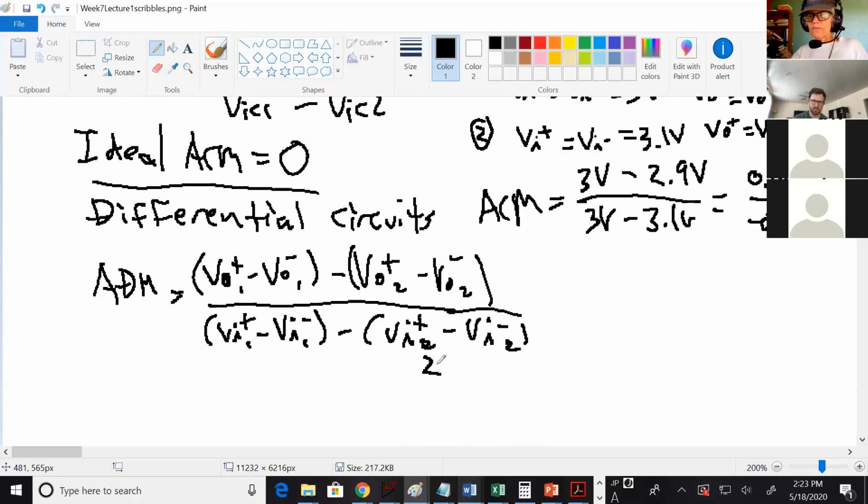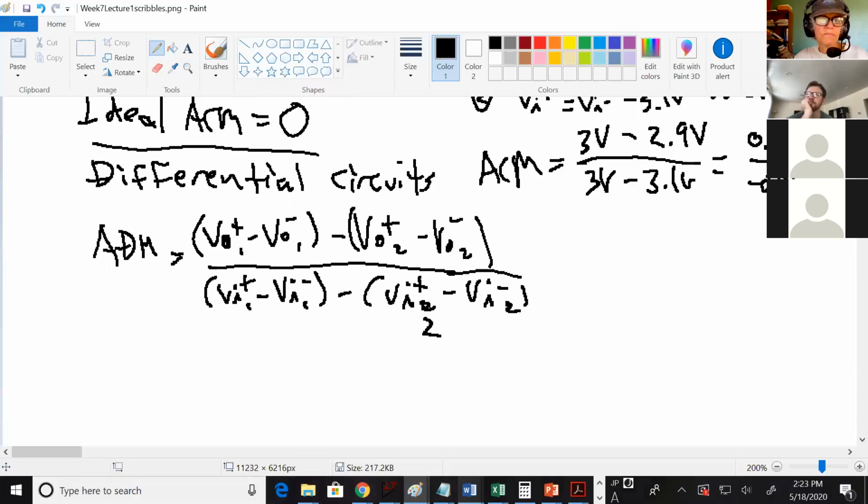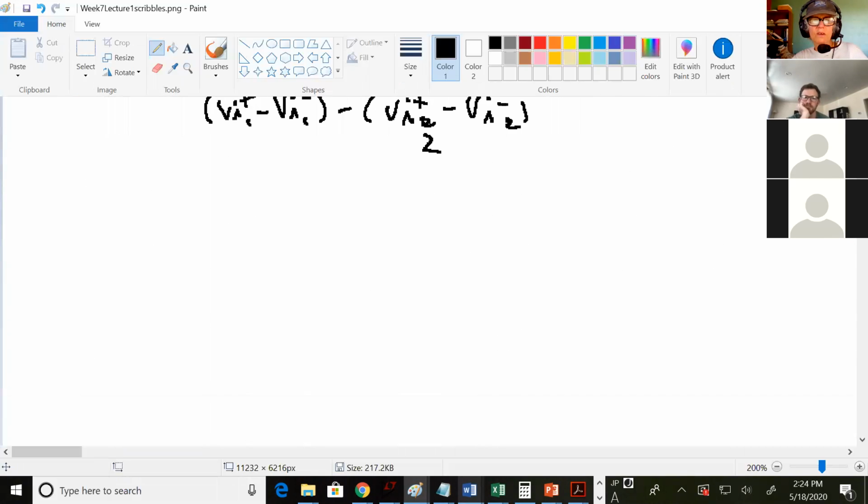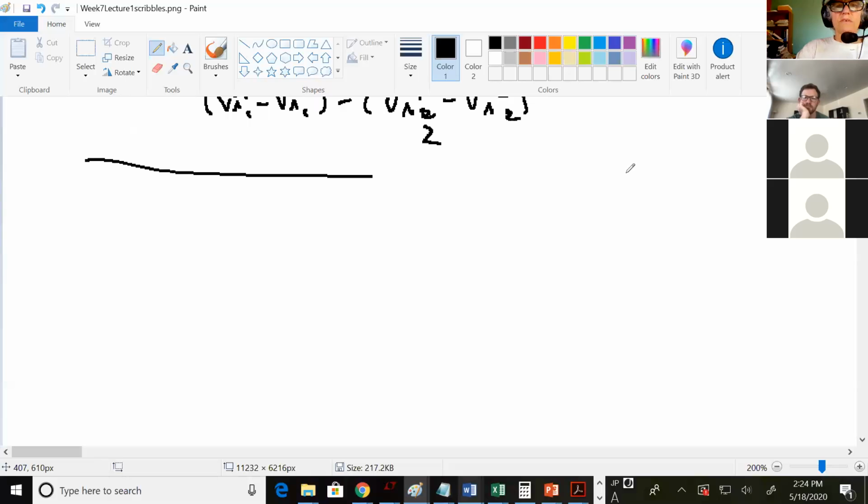And for those in the other section, in the second section, we actually got to this derivation for the theoretical. In other words, the theoretical gain for a common emitter is minus GM times RO in parallel with R. So I already went through the math for that in the second section. So that's what I'll do next here. So that's if you're in the lab or you're using LTspice and want to manually find ACM. Okay, so the theoretical ACM.